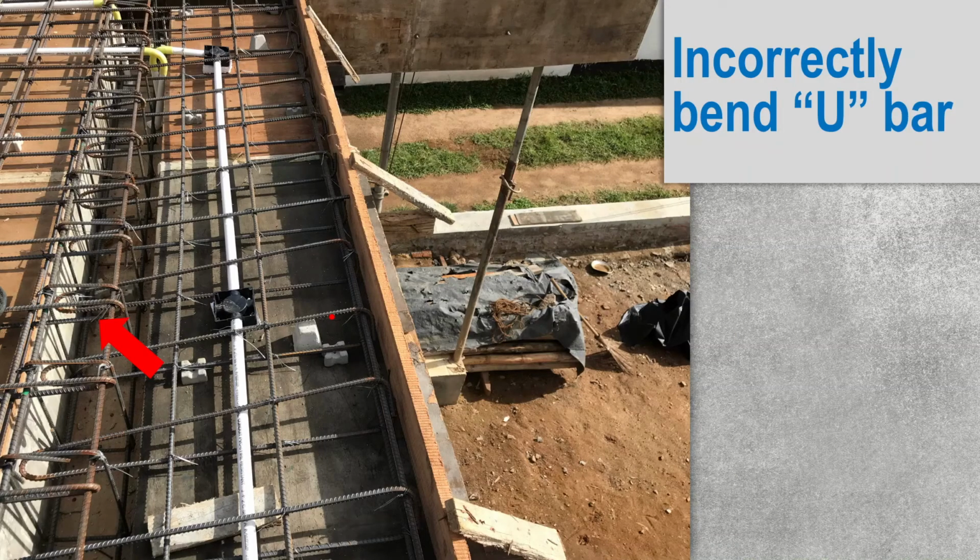Can you see the shape of the U-bar? It is not a properly bent U-bar. It's like a V shape. Here you can see the height, so at the support also we should have the same height. If they had done it correctly, this should go up like this, and this should go like this. This is the way. The same height here, the same height should be here.